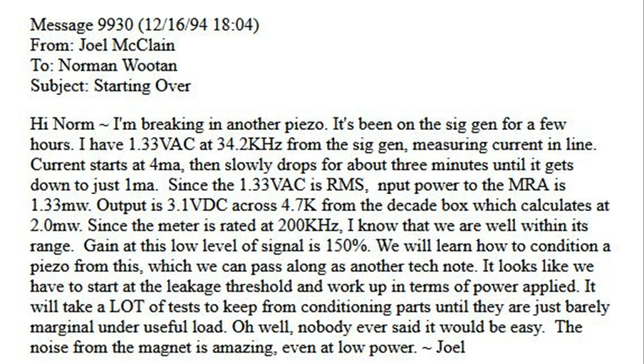We will learn how to condition a piezo from this, which we can pass along as another tech note. It looks like we have to start at the leakage threshold and work up in terms of power applied. It will take a lot of tests to keep from conditioning parts until they are just barely marginal under useful load. Oh well, nobody ever said it would be easy. The noise from the magnet is amazing, even at low power.